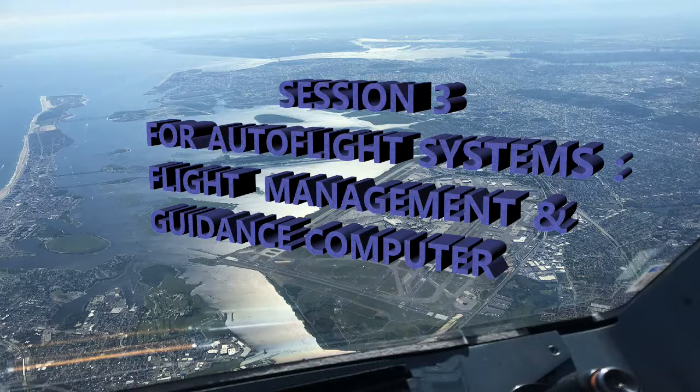Obviously, you're familiar with BITE. You always have the BITEs with these systems, and so we have this with the Autoflight system. When we mention the Autoflight system, it's a type 1, which just enables it to have two-way communication with the centralized fault display interface unit, your CFDIU. So you have that. And the other BITE, you've also got your FAC, FM, and FG BITE.